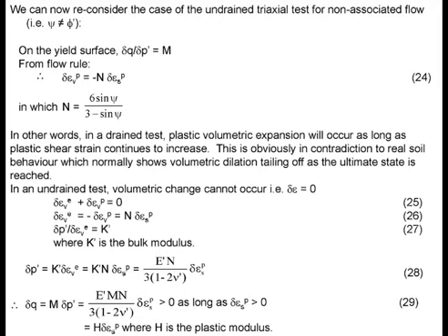So instead of m squared, as in here, all I have is m times n, which is here. You see? So if n is 0, if the dilation angle is 0, then what would happen to the stress strain curve? Q will just flatten out. There's no delta Q. Delta Q will be 0. So the moment you yield, the line will just go horizontal. Now that is more like the elastic perfectly plastic situation. That is why programs like Plaxis by default will give you a 0 angle of dilation, because in most cases it is the most conservative. Is that okay?